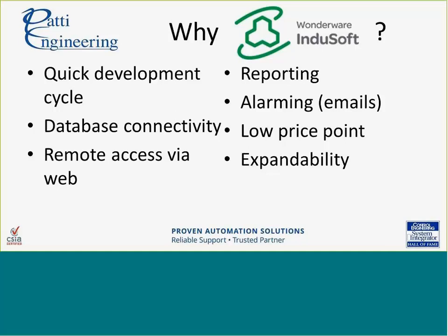Generating reports. I actually used some sample applications as a seed project for generating the actual physical report. Alarming, like I said, the email notification to let people know that stuff is out of spec. And low price point. It was a small project. There's only 10 or so temperature zones, so getting a big SCADA system is not really what we needed.